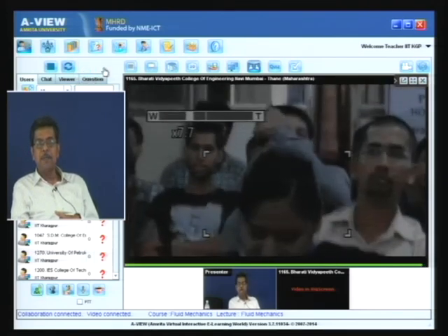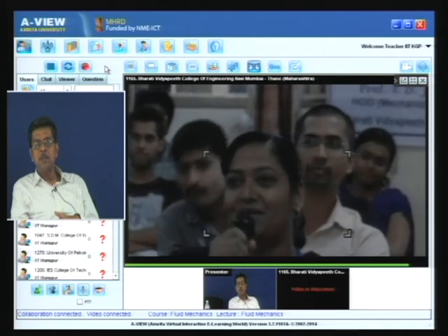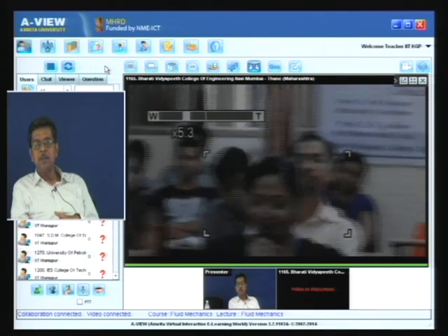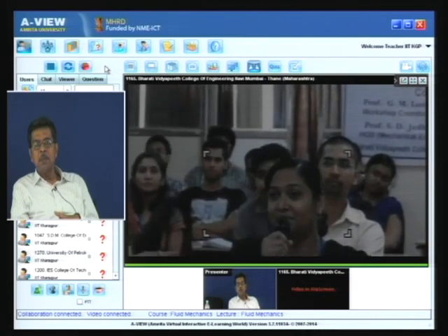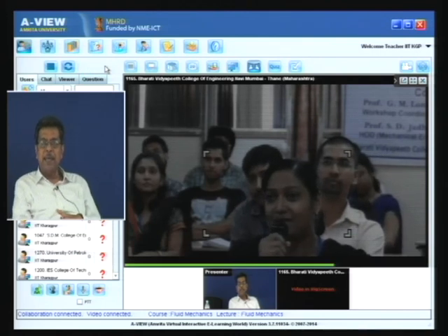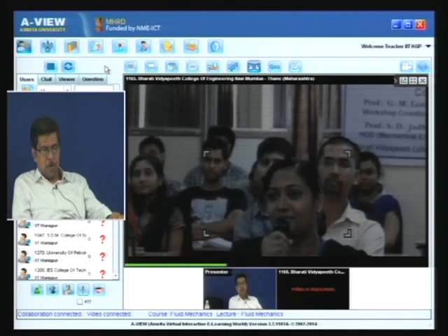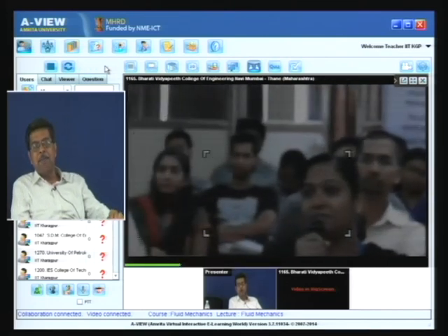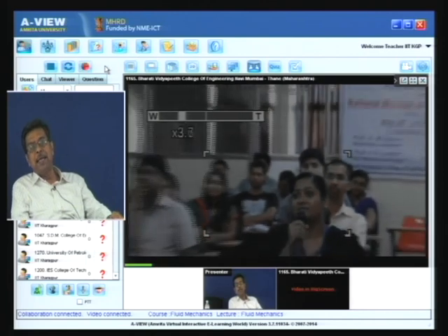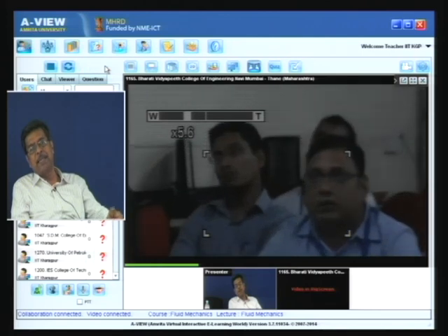Hello, sir. RTT applies the integral method of analysis, sir. Is there any alternative method utilizing the integral method of analysis, sir, except RTT? RTT relates the laws of physics from the control mass system to the control volume system, and this is written in terms of an integral form, yes. But we write the integral form of the continuity equation, which is the same as the conservation of mass by RTT. They are the same actually.